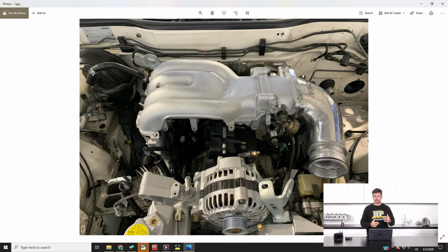The reason being that there's essentially 3 butterflies inside of that throttle body. Obviously we can't see that right now, and they run as sort of a primary and secondary style. Their opening is synchronized. They don't all open at the same time, and I wanted to retain that if we could, so going to a single throttle body really wasn't going to cut it for me.